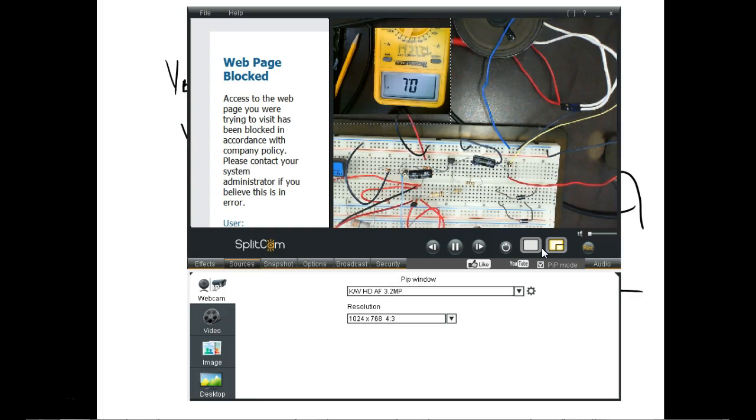But the smaller it is, so when you're dealing with these coupling capacitors, they're going to be a pretty good size because we want them to have very low opposition to AC, right? You understand? So this is 100 microfarad. So it charged up, but eventually it should go to what? Now the smaller ones, you get these little small capacitors, they'll charge up and measure open right off the bat. But these big capacitors, and then we swap them around, you'll see it actually go negative because the capacitor actually was charged up.